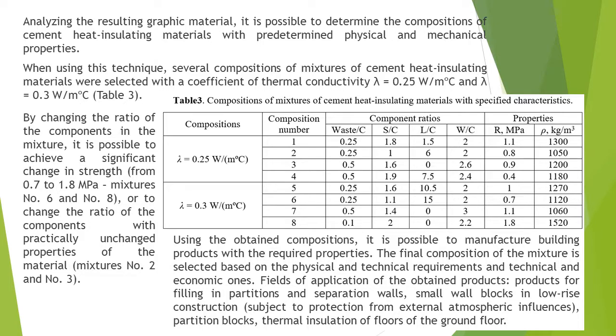Analyzing the resulting graphic material, it is possible to determine the compositions of cement heat-insulating materials with predetermined physical and mechanical properties. When using this technique, several compositions of mixtures of cement heat-insulating materials were selected with a coefficient of thermal conductivity of 0.25 and 0.3.